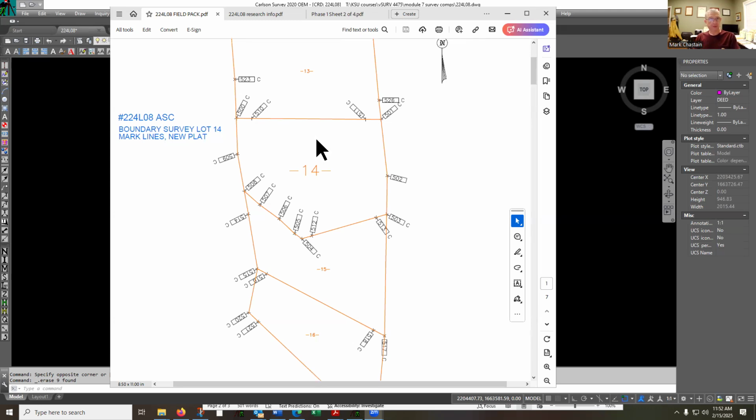I'm going to set up this instrument, or they find one pin, whether it's an actual corner or not. Sometimes you just don't know. And they just go about turning angles, assuming north meridians, and putting pins in the ground. A lot of times people see those. They build fences to them. They drive posts or stakes by them. And when you arrive on the property, your natural assumption is these are the corners.